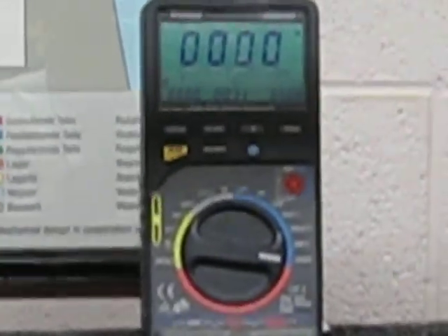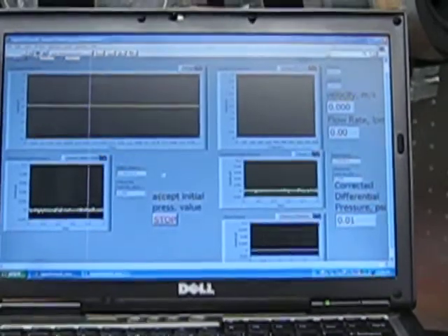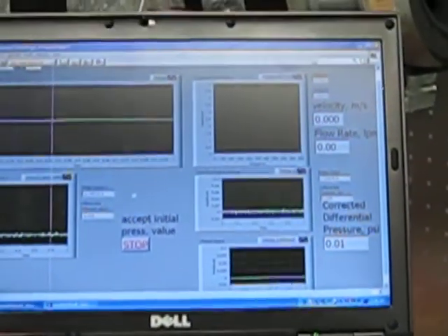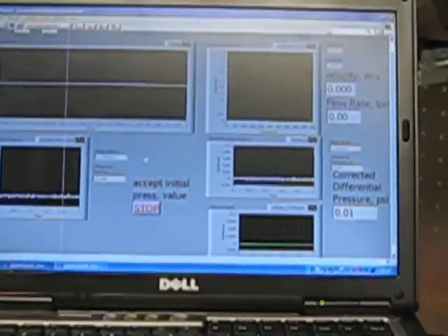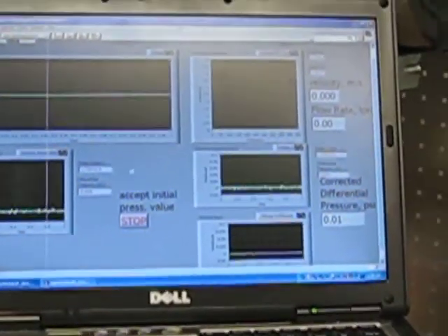The rest of what's here, there's a power meter hooked up. This will give us the power that the system's using in watts. There's a LabVIEW program over here that's coupled with a flow sensor and pressure transducer, and this will give us the volume flow rate, liters per minute, and the pressure differential, pounds per square inch. What a bummer, inconsistent units.